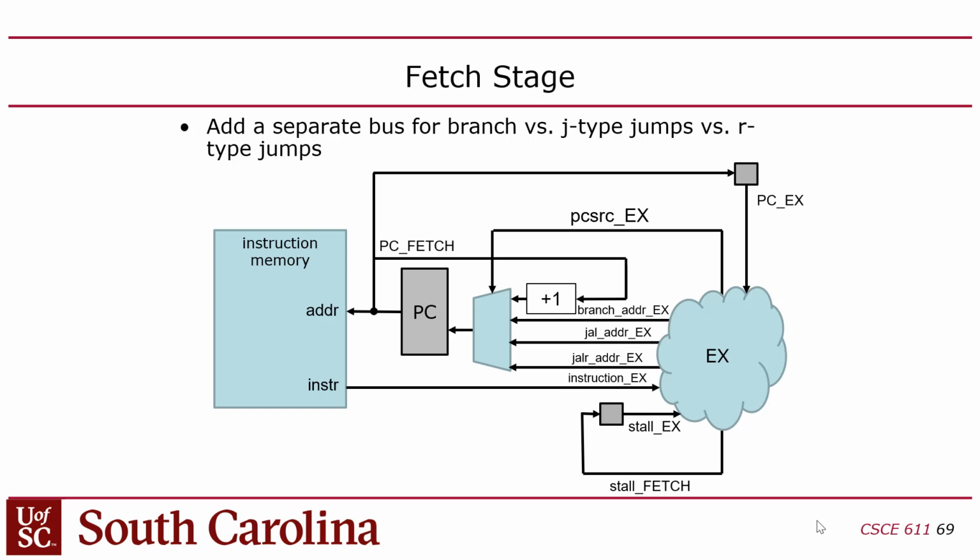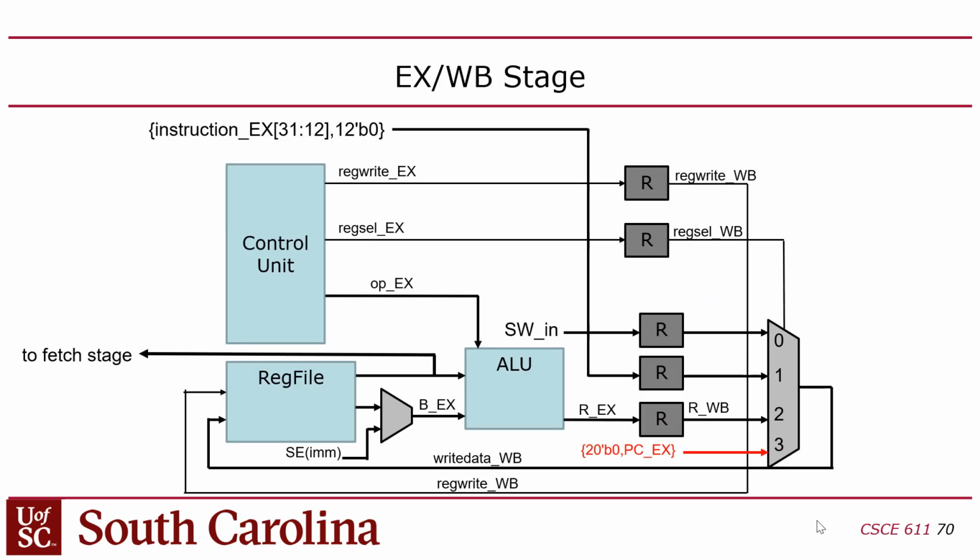And these are really hard to track down. If this happens and you have a loop in your code, there's really no way to diagnose it other than randomly commenting parts of your design out to try to narrow down where that loop is. You might say, come on, you just look for a loop. Well, no, because keep in mind, the loop might be passing through the hierarchy of your design. So sometimes it's not obvious where these loops are. Whenever this happens to me, I literally just comment out half my design and see if the loop is still there, and I try to do a binary search to narrow down where the loop is.